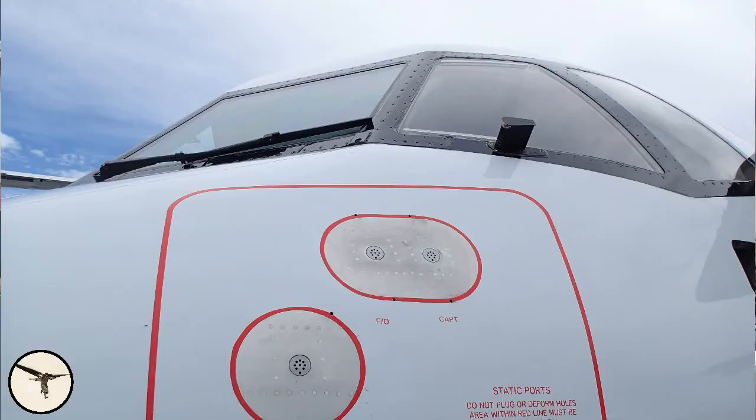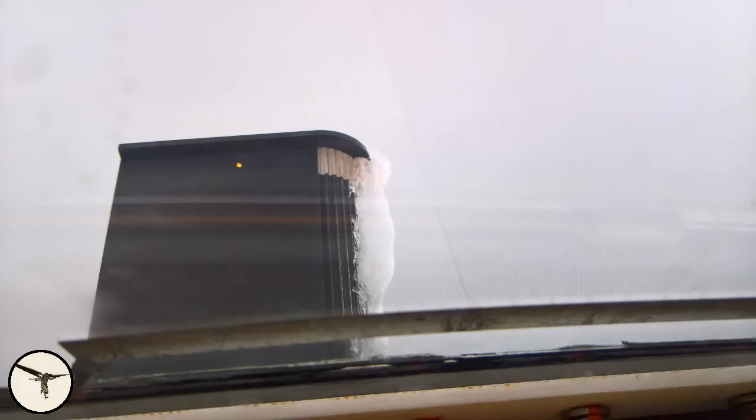3. Loss of performance, such as rate of climb or cruise speed. To assist detecting ice on the aircraft, an ice evidence probe is installed below the captain's side window. It is shaped like a small wing profile. It has an internal light, which is illuminated when the navigation light is on. As long as there is ice on the ice evidence probe, we must consider that the other areas of the airplane are contaminated by ice.